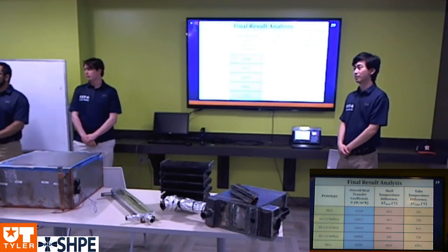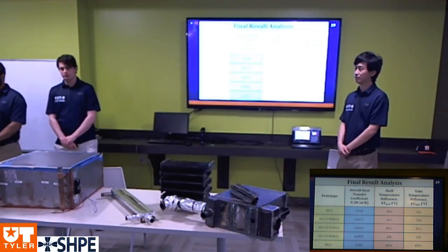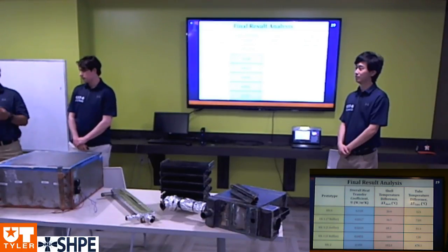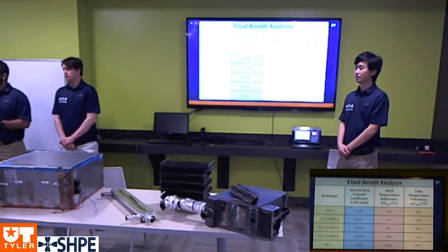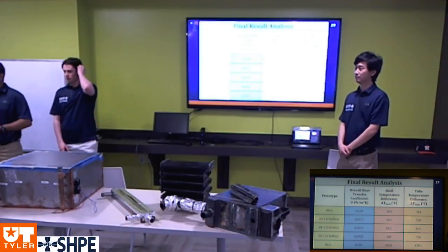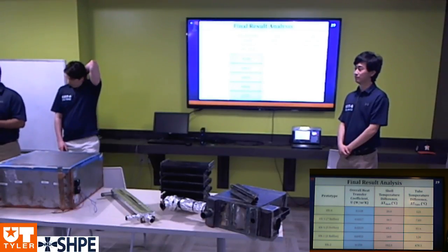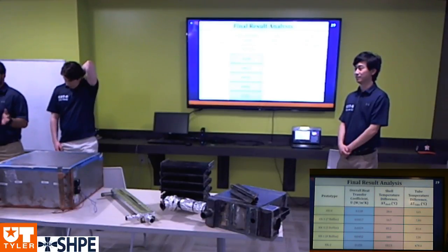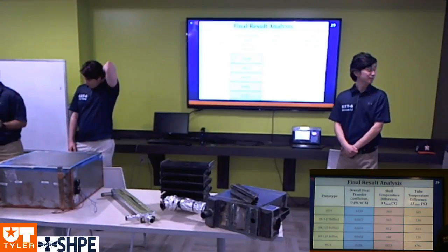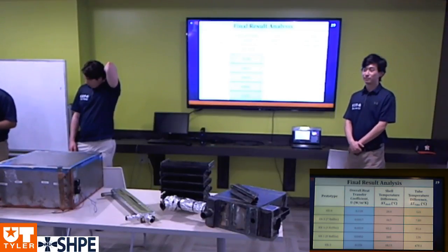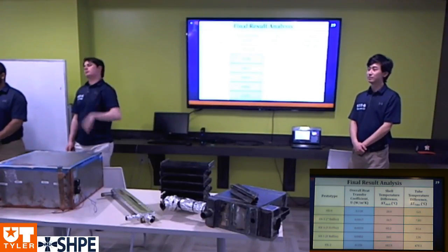The reason we were looking for just temperature is because the whole point of the heat exchanger is to preheat the air and save on power for the heater. So if we have 25 degrees Celsius air coming in and 200 coming out, that's 180 that the heater doesn't have to heat up. And that's power. Power is money. Over time, it ends up saving a lot.